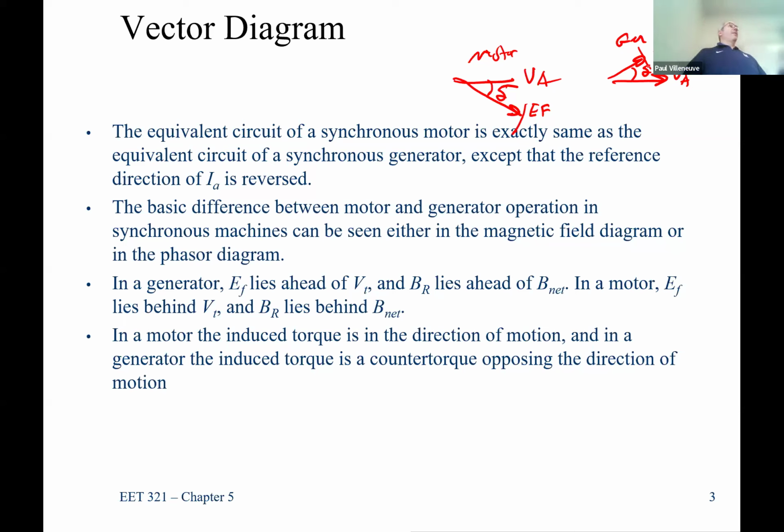And the torque that exists, right? Because you're having a motor, you have to have a torque that's rotating whatever mechanical system you want. You have to have an induced torque on the electrical system so that they will balance each other out. You've got electric power going in, that's being converted to mechanical power, but there has to be an equivalent induced torque because of the electrical power flow so that you can actually provide torque. And that's okay because power equals torque times omega. As long as you have power and you have speed of rotation, you've got a torque.